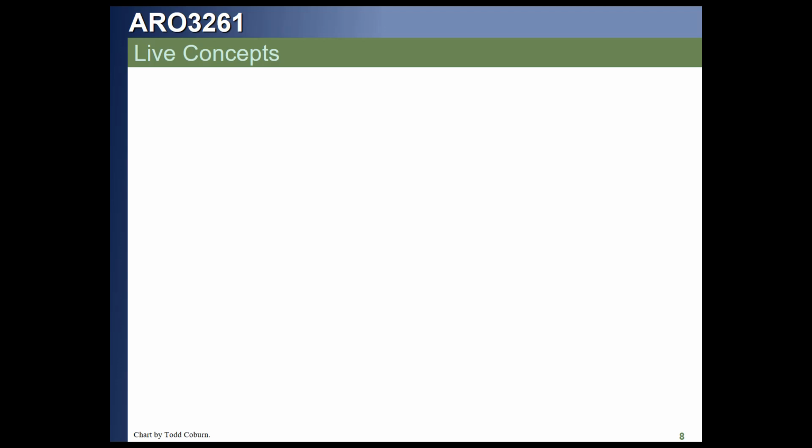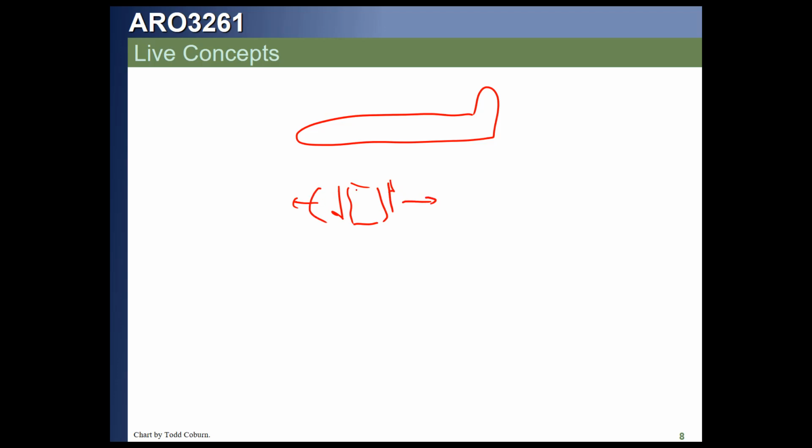Does that make sense? So, how do we apply this principle? Well, if we have a fuselage, we can analyze that fuselage for whatever bending load and shear. So if we take a little segment of fuselage, we're going to have a bending load, an axial load, and a shear on it. That means any little stress element that we pull out of it will have axial load and shear.